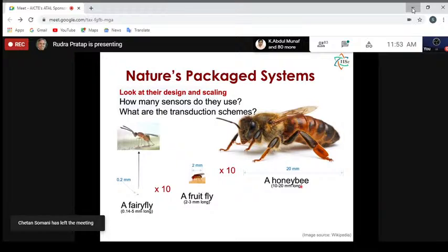G switches. G switches are accelerometers, which are threshold accelerometers that only if a particular level of acceleration is sensed by it, it engages like a switch here, okay? So this is used for triggering an event. That's what switches are for, right?